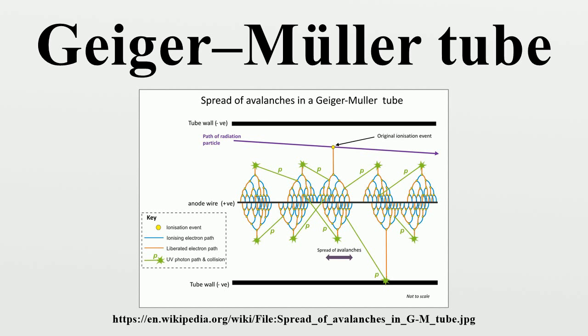Some of these electrons are produced close enough to the inner wall of the tube to escape into the fill gas. As soon as this happens, the electron drifts to the anode and an electron avalanche occurs, as though the free electron had been created within the gas. The avalanche is a secondary effect of a process that starts within the tube wall. The avalanche is not the effect of radiation directly on the gas itself.